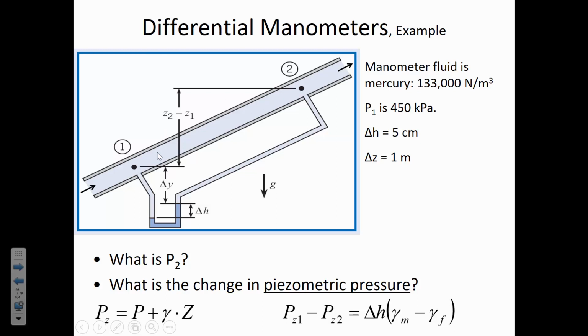Part of the reason why the pressure at 2 is lower than the pressure at 1 is because of that pipe friction I was talking about earlier. And although we're not yet at the point where we're going to calculate how much pressure loss there is in a pipe, we should mentally still be able to understand and keep track of the idea that pressure decreases in the direction of flow due to pipe friction.